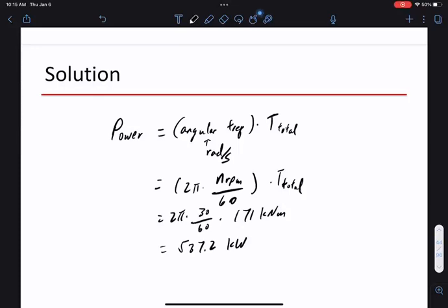Another reason is the mechanical stress. These blades are really big. The tower is really tall. You have to withstand a lot of force. If you build more blades, it becomes too heavy. And you cannot build blades as large because of mechanical stress. Okay, so 3 is sort of the right trade-off.